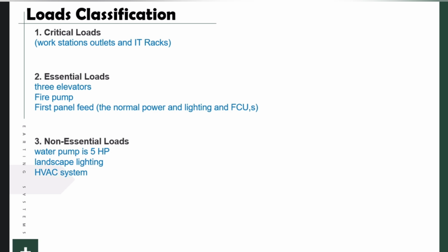the first panel, which is feeding the normal power and the lighting and the FCUs, fan coil. And for the non-essential load, I'm also selecting the water pump and the landscape lighting, in addition to the HVAC system.